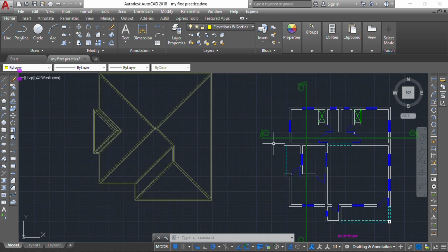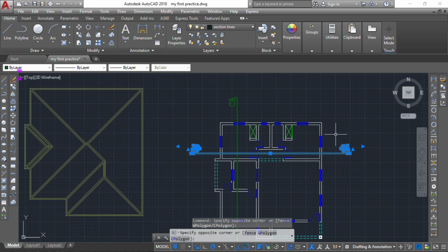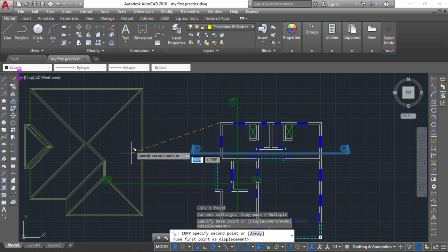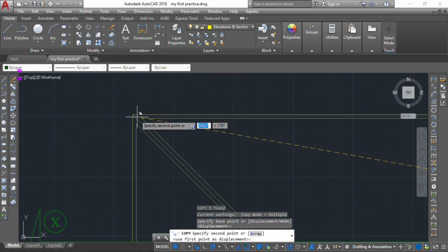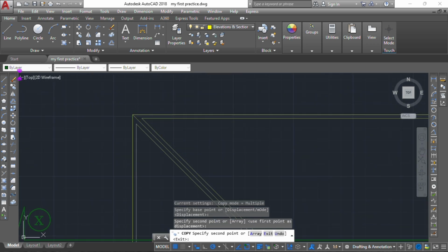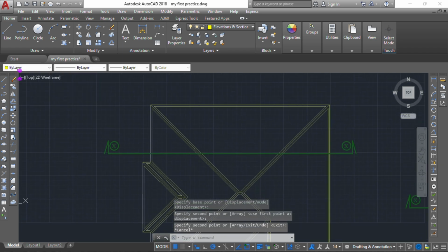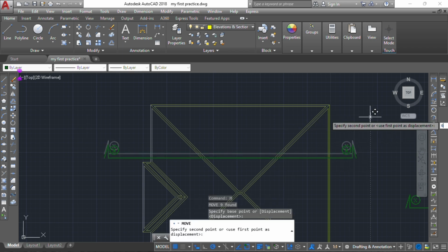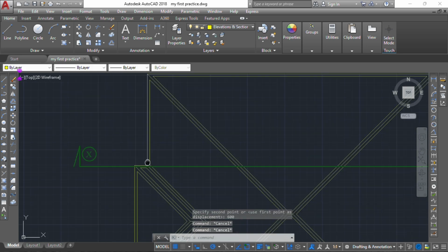Okay, let's just copy this to see it properly. Let's copy it and bring it here. But you know, our roof is having the eaves already, right? So let's just subtract the eaves from it to get the exact positioning of this our sectional area. So now let's move it down to the distance of 600, right? So we are having here.